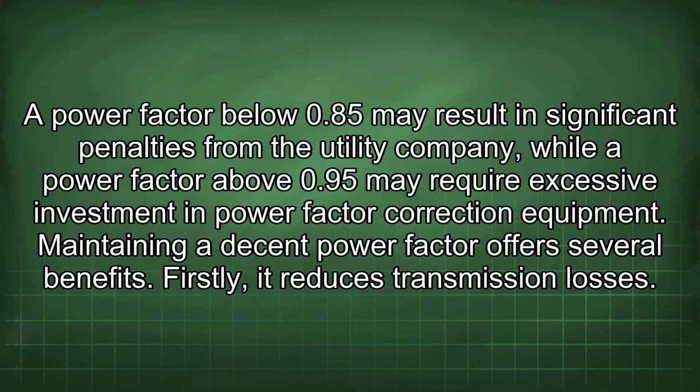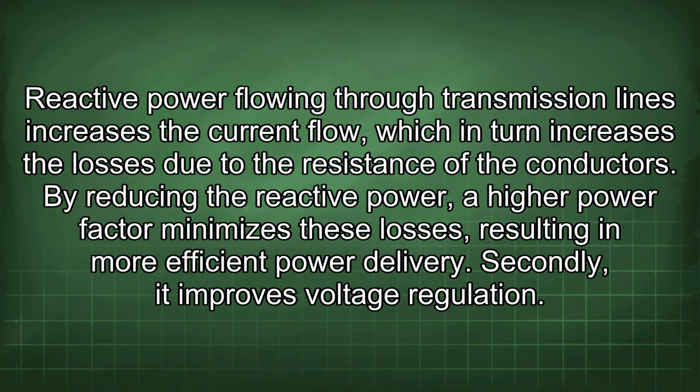Maintaining a decent power factor offers several benefits. Firstly, it reduces transmission losses. Reactive power flowing through transmission lines increases the current flow, which in turn increases the losses due to the resistance of the conductors. By reducing the reactive power, a higher power factor minimizes these losses, resulting in more efficient power delivery.